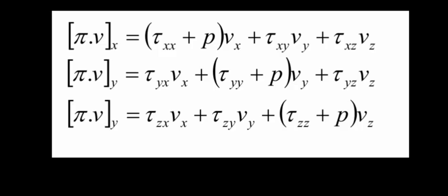These terms represent the rate at which work is being done by the viscous stresses as layers of the fluid move relative to each other. This work, as we'll see later, can contribute to the heating of the fluid. Think about stirring a viscous liquid like honey. You're applying a force, and the different layers of honey move at different speeds. There is friction between these layers, which is related to the viscous stresses. The work you do in stirring is being transferred through these stresses and ultimately contributes to a slight increase in honey's internal energy, a form of viscous heating.